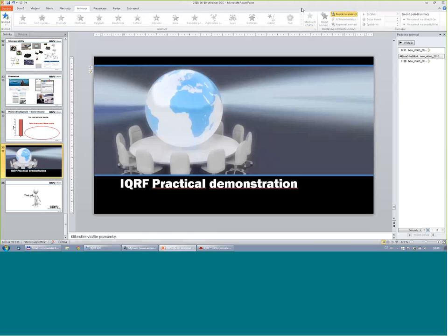Okay, so the frequencies we are using are especially 868 and 916 megahertz, so sub-gigahertz. Also, the 50 series modules work on 433 megahertz, and on the 70 series, the red modules, we will also open new bands, but this is not fixed. So far, the red modules use 868 and 916 megahertz.